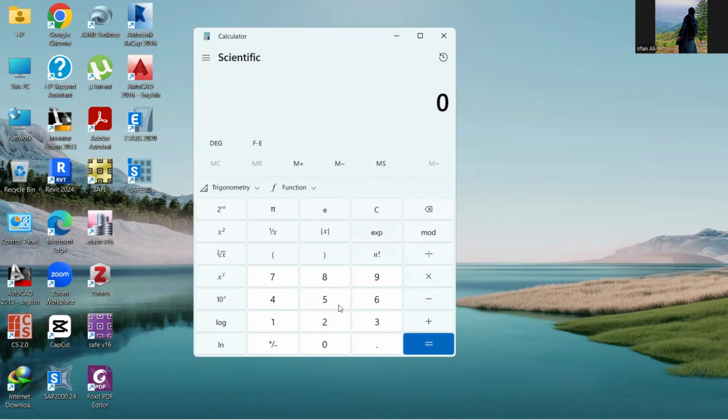For example, if I take our building, which is 12 feet, and in the 12 feet we have no support, for example, the beams are not connected within the 12 feet because we have a 12 feet story height. So if you convert it into inches, it will be 144 inches. If you divide it by 25, the minimum thickness for the shear walls and lift walls is 5.76.